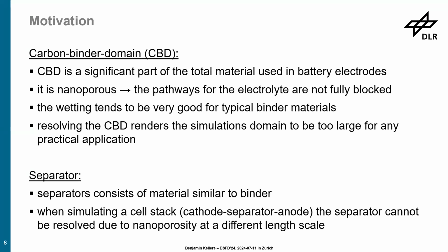The nanoporosity leads to the fact that the electrolyte is actually often so wettable that it can intrude the binder and can go through it. So these pathways are actually not blocked for the electrolyte. They just slow down the filling process. Yeah, wetting is typically very good for binders. You talk of contact angles as low as 8 degrees. And yeah, resolving is just not possible.